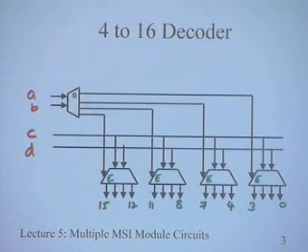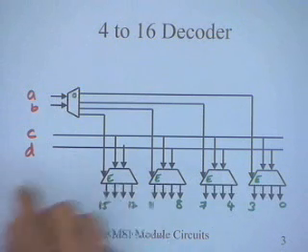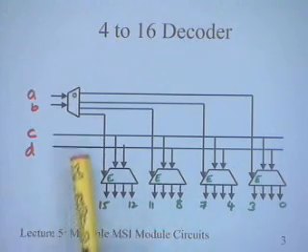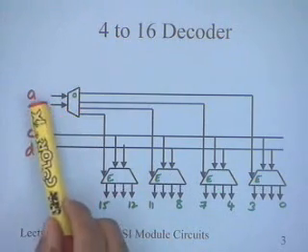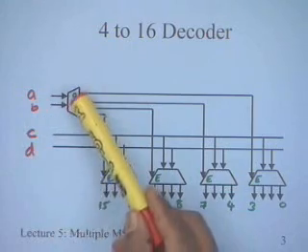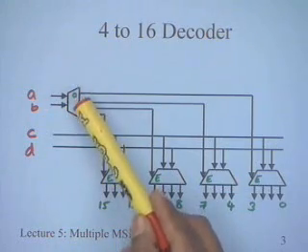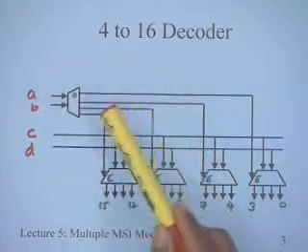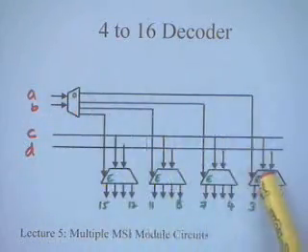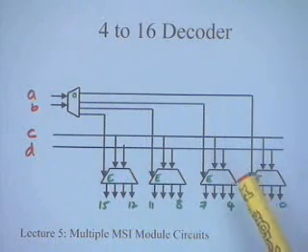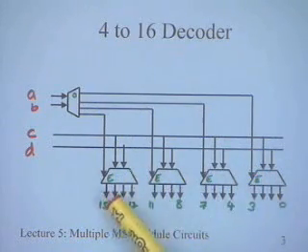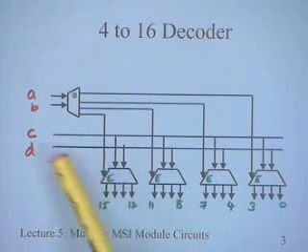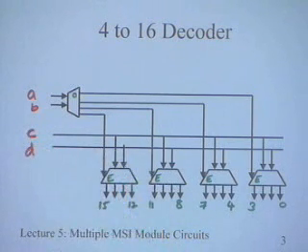This type of logic is called tree decoding logic, because we have a tree. I will try to show it drawn like a tree, but in this case you can see that this particular decoder is just decoding variables A and B, and is generating the 4 combinations 0 0, 0 1, 1 0 and 1 1. These outputs correspond to those 4 combinations, and depending on which one is active, one of the output decoders is going to be selected. Which output is actually active depends not only on the decoder being enabled, but also on C and D corresponding to the output.